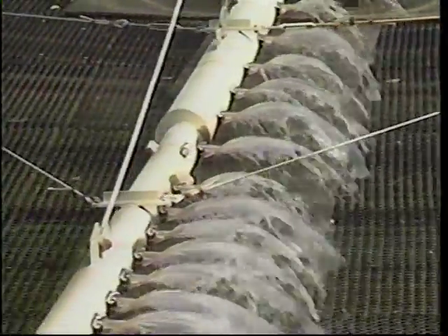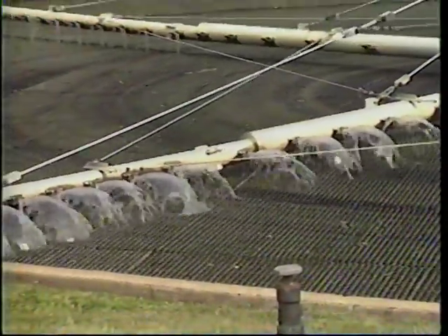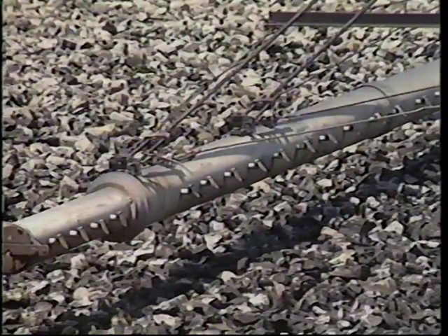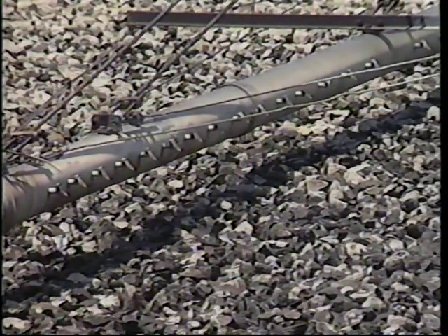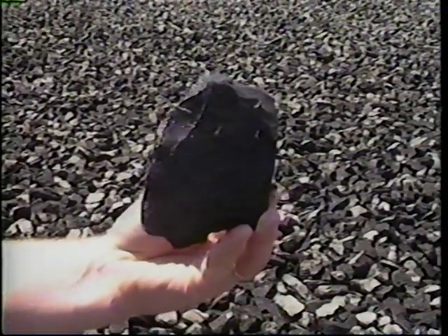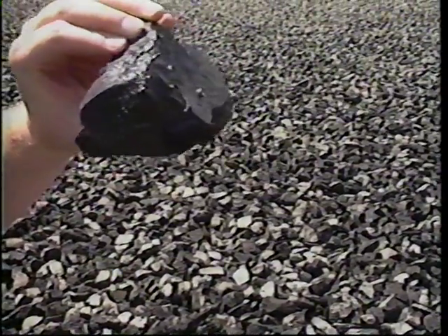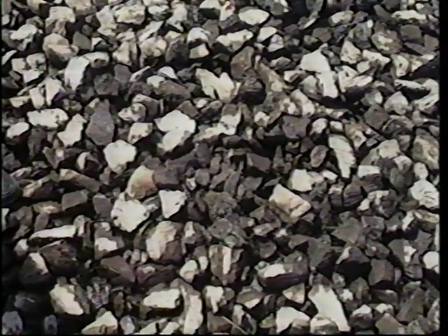Next, we will look at the media in the trickling filter. The media provides surface area for microorganisms to grow and feed on the organic matter in the wastewater. In all trickling filters, the media is either a stacked type or random dump type of media, such as rock. Random dump media should be uniform in size to facilitate airflow through the media. As the name suggests, this media is dumped into the filter up to the desired depth. Random dump media may also be made of plastic or other materials.